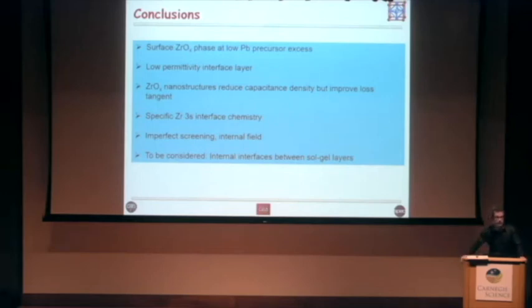Nice talk. Thank you for doing these measurements on those nanoparticles that the community has often thought are pyrochlore. One quick question. When you look at the orientation of the films, if I understood correctly, you seem to suggest that when you do not have enough excess lead, you do get a 1-0-0 orientation. This seems to be somewhat contrary to a lot of other literature reports in which, when there is higher excess lead, you do get more oriented films because the lead oxide excess is a seed layer and therefore allows a 0-0-1 orientation. Can you comment on that?